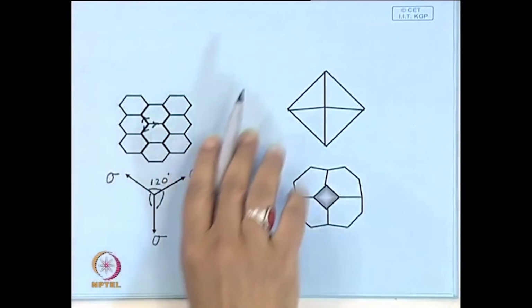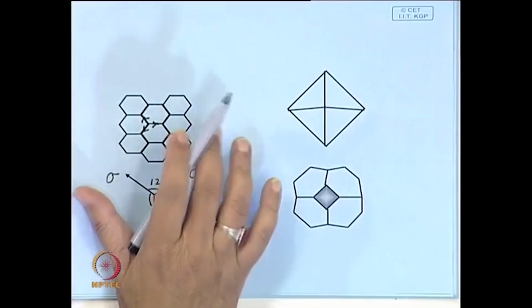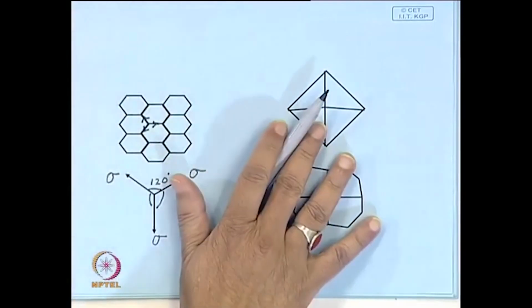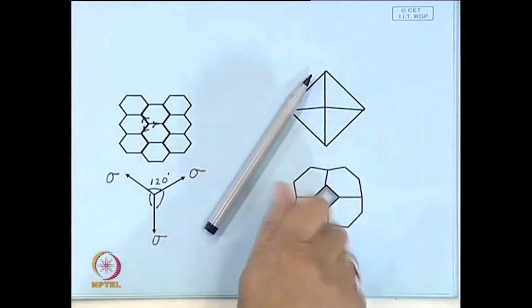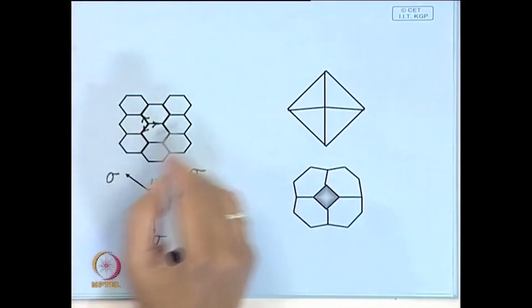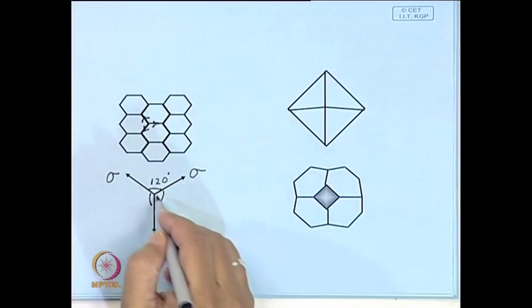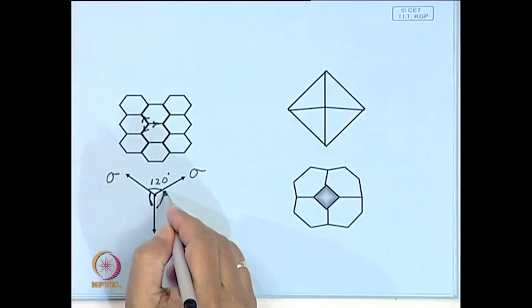So, therefore, it is not that the grain surface energy of the crystal on every surface is the same, but the difference in surface energy with respect to the orientation, the magnitude of this difference, possibly is very small. So, whenever you look at a 2D structure, the simplest experiment to do is with a soap bubble. If you take a ring, put it in soap water, and take it out, you will find that the soap bubbles which form, that is a 2D structure, they all will be like regular hexagons, and it maintains this equilibrium.